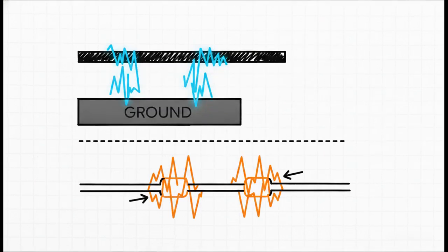On the flip side, we have to deal with capacitance. These are our unwanted energy storage tanks, and there are two main types you really need to look out for. First up is ground or substrate capacitance. This happens basically any time a metal wire runs over the substrate. The second is coupling capacitance, which flares up when two wires are routed right next to each other, interacting through their electric fields. Now, coupling capacitance is a massive headache, especially in sensitive circuits. Picture this, a noisy digital clock line running parallel to a delicate analog bias voltage. That coupling capacitance will literally inject high-frequency noise right into your clean analog signal. It completely destroys your signal-to-noise ratio.